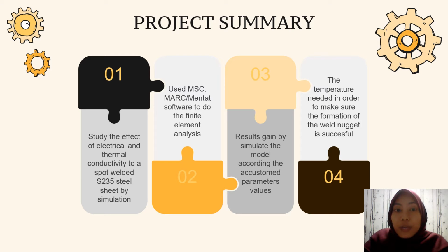So basically what I'm doing is studying the effect of the electrical and thermal conductivity on the metal sheet using the resistance spot welding model. Resistance spot welding is one of the ways to join thin workpieces where the thickness is less than 3.5 mm. There are many parameters that need to be considered when using resistance spot welding.